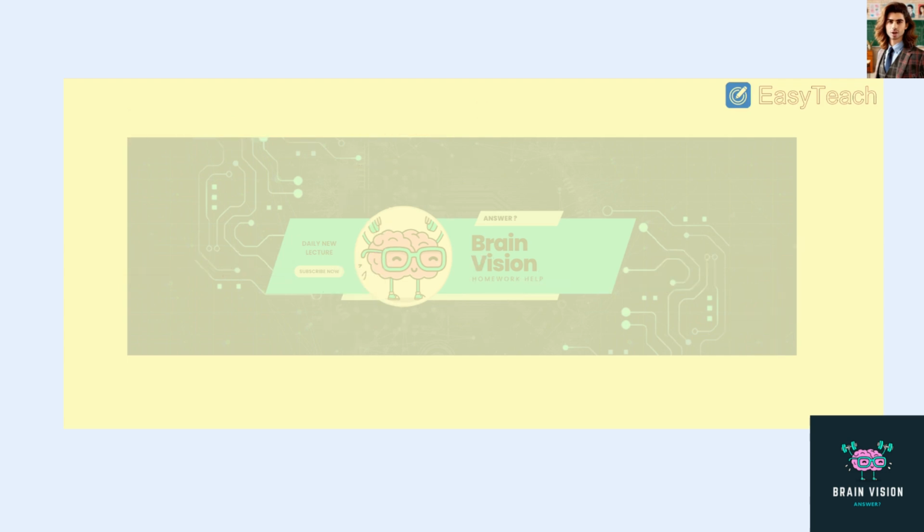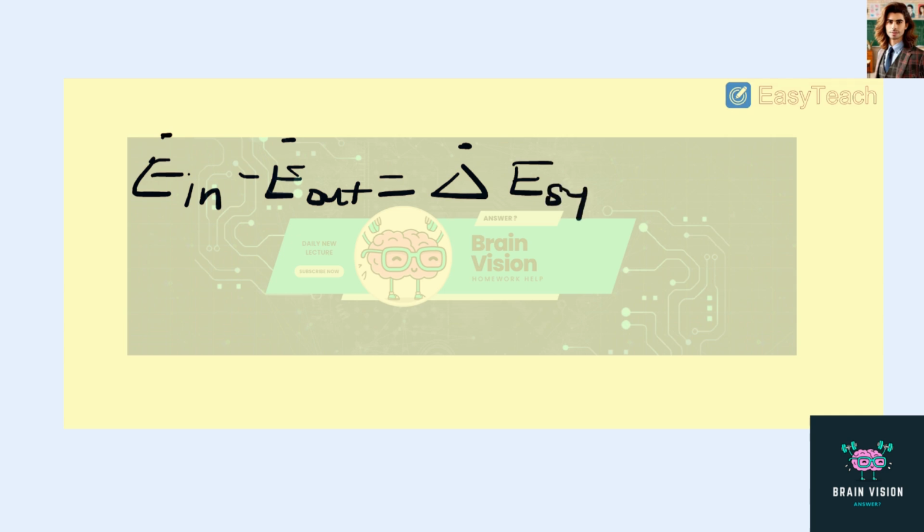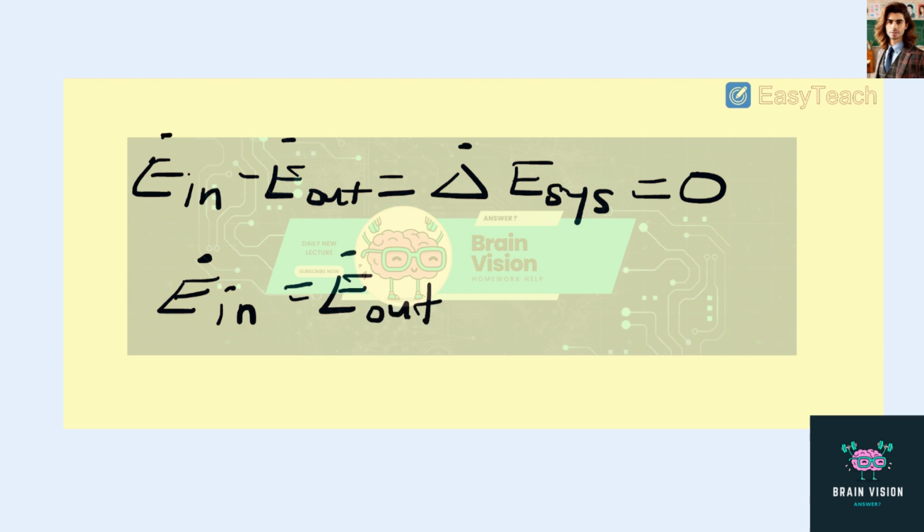So we're going to define our system as the turbine, and that's also going to be our control volume. When we do our energy balance, we can say that the rate of energy coming in minus the rate of energy leaving is equal to the total rate of energy change in the system. However, as we stated before, we're dealing with a steady state operating condition, so therefore this will be equal to 0. So we can say that the rate of energy coming in is equal to the rate of energy leaving the system.